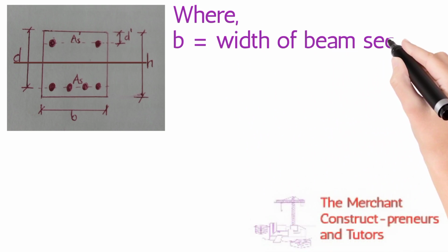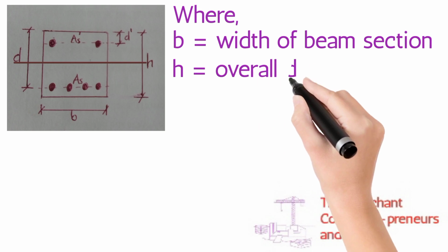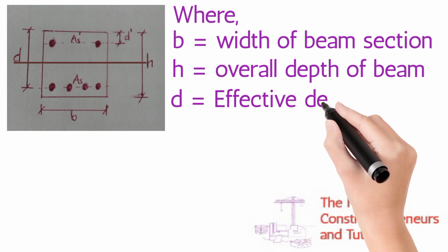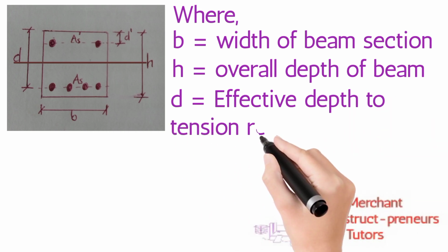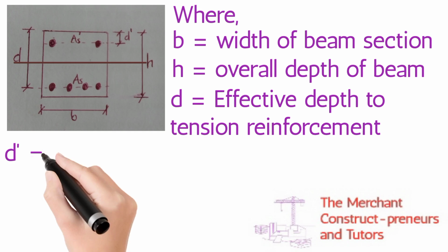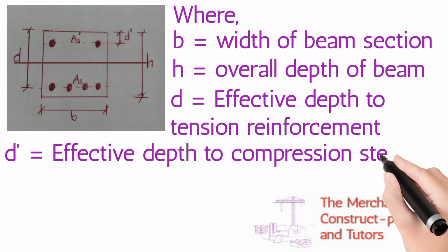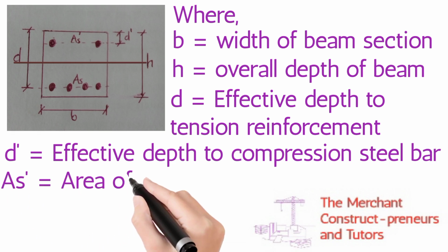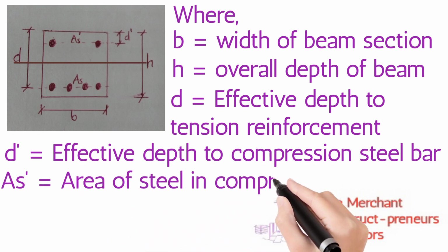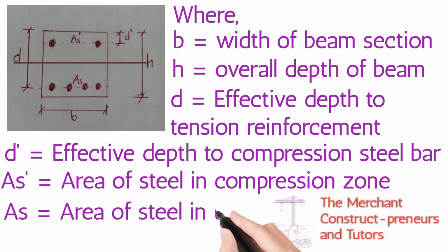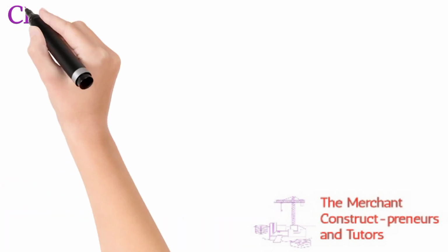The beam section should be designed as doubly reinforced, because once anything has passed the ultimate moment, the next point is the breaking point. So if your design moment is already higher than the ultimate, then you just have to provide the reinforcement at the top, and that reinforcement at the top is to resist those moments and then bring it back to normal. So the first one, singly reinforced, you design the reinforcement for the bottom only. The bottom tension area can actually cater for the design and the ultimate moment, comparing the design moment to the ultimate moment. But for this one, this doubly reinforced, the bottom alone cannot do it, so we have to introduce the top.